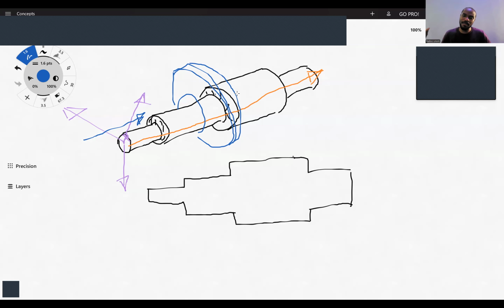Okay, so you fit them and they run until they stop and you can lock them there. If it's an interference fit, you keep pushing it until it stays there and it stays permanent. If you're using a key, you fit it to that point and your key is there to lock it in place. All right, so shaft shoulders provide a means of axially locating your shaft elements. Okay, going to go back to my slide.